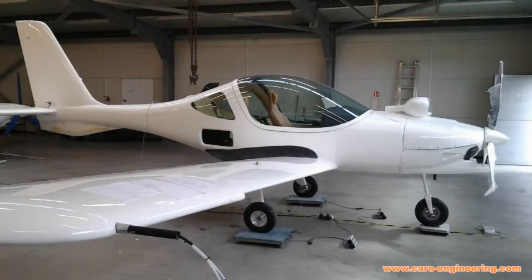First of all, we will rehearse how to determine it on an existing airplane with the whole airplane set up on scales. Set the scales to 0, then roll the airplane up. It needs to be leveled, that means the waterline or x-axis is horizontal. For this example, I use a nose gear airplane and the reference plane is at the wing leading edge at the root, so anything forward of the wing leading edge has a negative fuselage station.